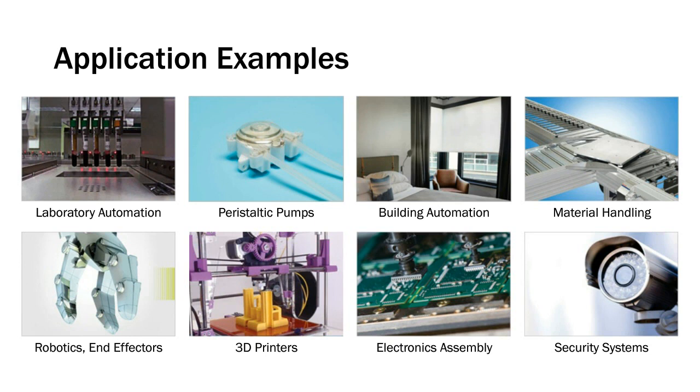Peristaltic pumps is kind of an interesting one because peristaltic pumps, especially smaller ones, are often driven by step motors, and it works out great. And in most applications, the fact that the open loop step motor runs hot is not an issue. But in some applications, the heat from the step motor actually causes problems because it heats up the media in the tubing that's running through the pump, and that can mess up processes downstream from the pump.